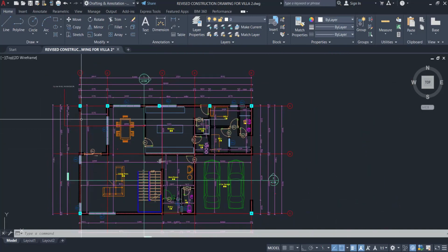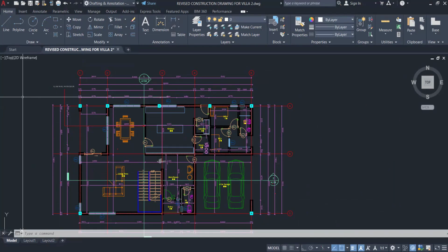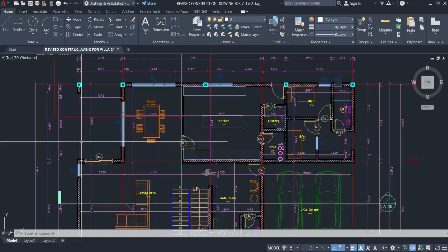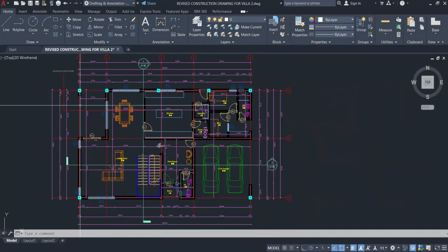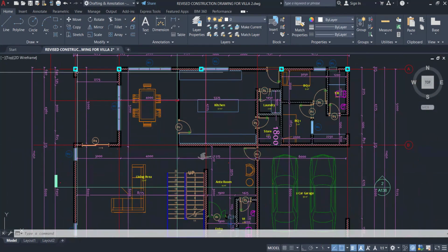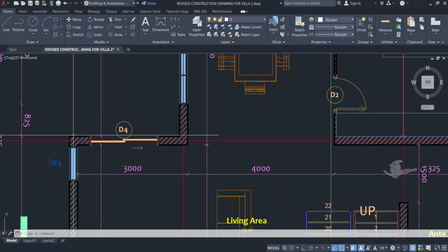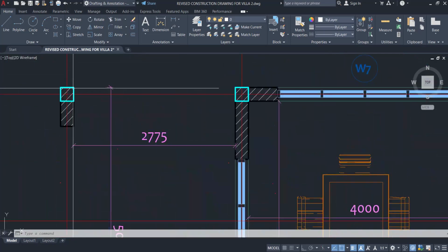So on grid line B, it is not compulsory that you use the grid line as I'm explaining it. Sometimes it depends on the shape of the building. Between grid line 1 and grid lines A and B, you see that there's no wall here at all, so I cannot put any column here. The next safe place that I can put a column on grid line B is this corner. So I will move my column.